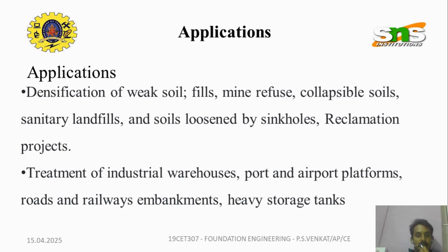So, to summarize dynamic compaction, it is a powerful and cost effective technique for improving deep soil layers and preparing the ground for safe construction. With the ability to reach depths up to 20 meters, it reduces the risks of liquefaction. It plays an essential role in modern infrastructure development.